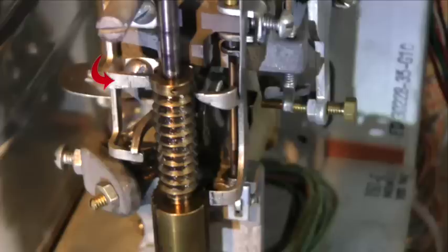This is the stationary dog, so called because it doesn't move. The upper leg of the stationary dog is engaged by one of the vertical ratchet teeth during shaft rotation. As such, this leg supports the shaft during its clockwise rotation when rotary stepping and during its anti-clockwise rotation when releasing. It also supports the shaft in its stationary off-normal position for the duration of the call. The lower leg just provides a stop for the released position of the vertical pawl.